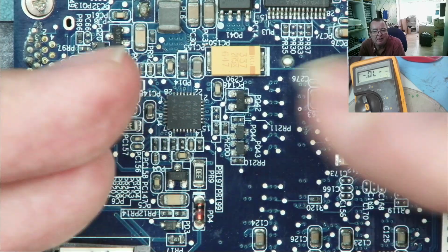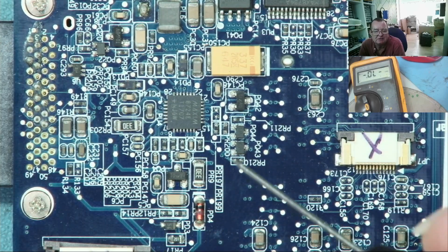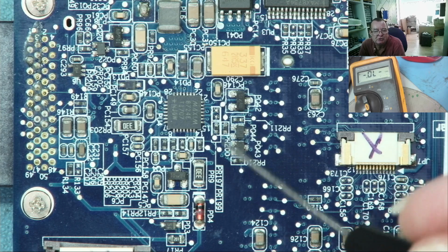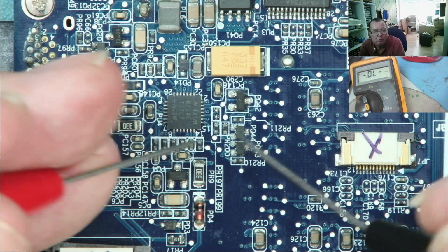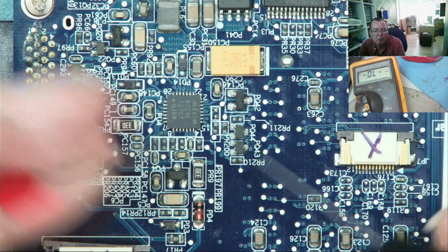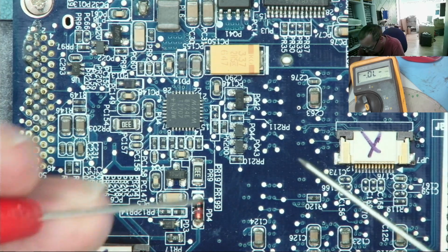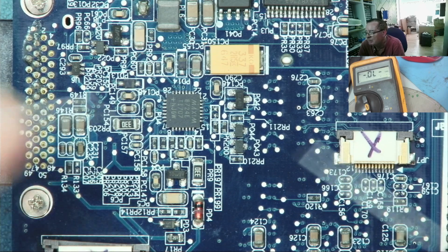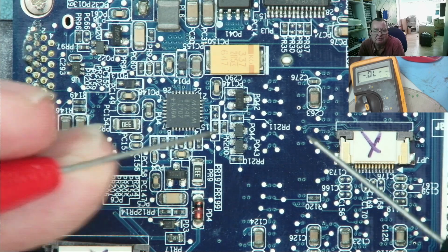So when you find something like that, that's a perfect example of checking the polarity, seeing if one end of these is ground or a power rail, and from that working out whether that junction you see is something that can ever occur in normal operation of the circuit.